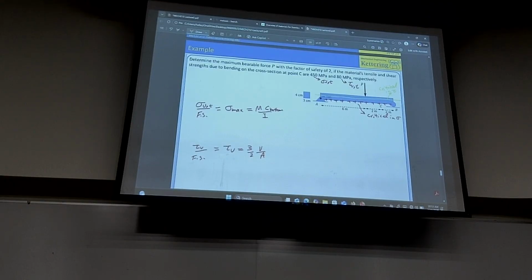All right, so Justin, if you recall, in bending, the first item was to put the coordinate system at the centroid of interest, right? Interest is point C. We have to put the coordinate system at point C, but at the centroid, the cross section is rectangular, that is right at the middle. So I have to put the coordinate system there. So right in the middle, these are the three axes that you go for, X, Y, Z.